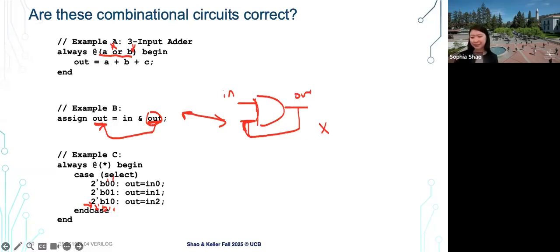How do hardware or the synthesis tool interpret this circuit? The tool will interpret that you want this behavior where for this particular 1-1 scenario, it is undefined. So I should maintain the values I had before, because nothing is changed when it has that input.